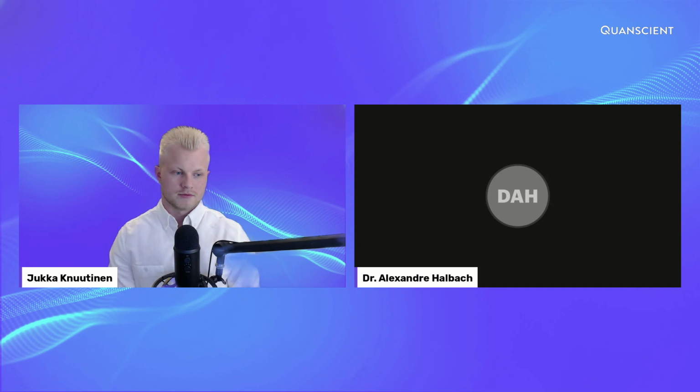That's a good question. So yes, it can. We have simulated everything from plain electromagnetic wave scattering with 40 million unknowns in air, and the interaction also with conductors. We also have done lots of antennas, such as dish antennas, for example, where you have radiation in air. And there's no limitation regarding this, and also no limitation regarding any geometrical shape. It's a finite element method, and it supports kind of the most general approach you can find.